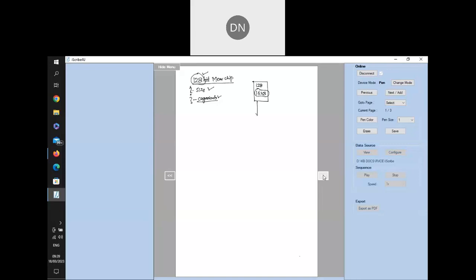Now let's see what will be inside any memory chip. I said there are 16 rows. We will call each row a word, so we use the term word line in the further description. Word line 0, word line 1, up to word line 15. Because memory is organized as rows and columns, each row is considered one word. Each row contributes one word of data. Now, there are 8 columns there, so I'll be writing 8.